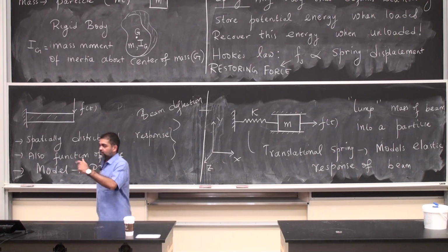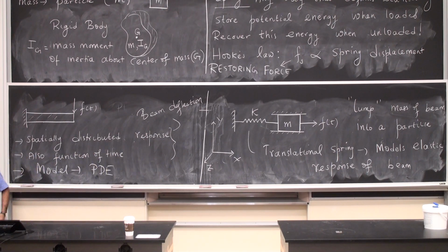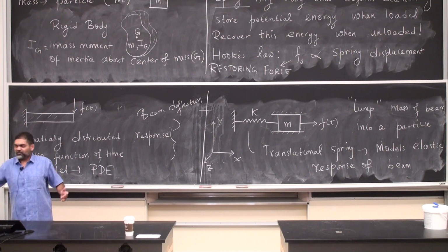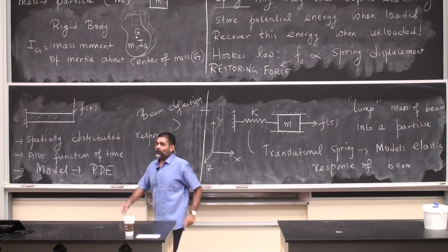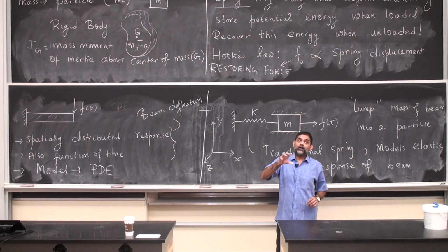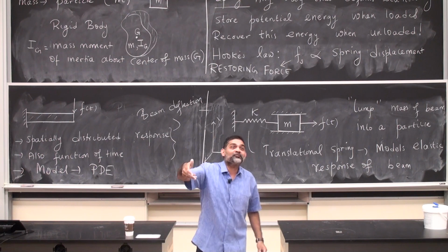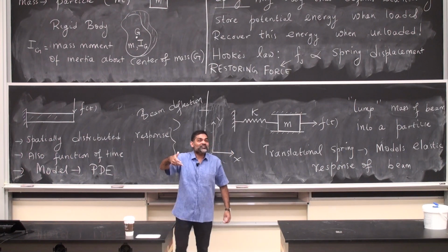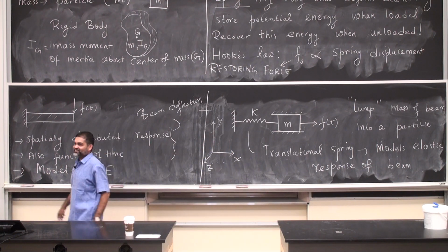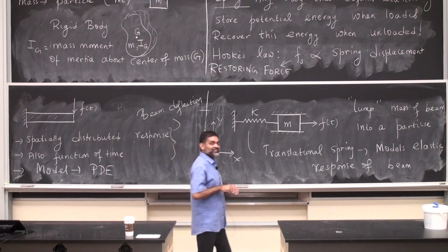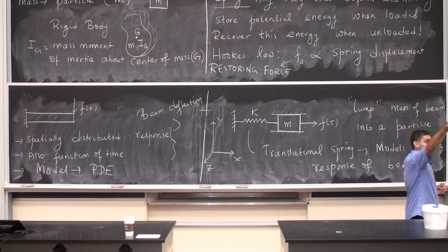Okay? So one of you had your hands raised. Why wouldn't you make it like a radial spring to make it more similar to the original problem of being deflected like that? I could just take that system and draw it upside down or vertically. That's fine too. Same thing. It's all the same behavior, right? Or I could do the following. Instead of a force acting on the cantilever, I take the end of the cantilever and twist the heck out of that guy. I can then model this as a torsional spring. Or I could have a combination of both a torsional spring and a translational spring.